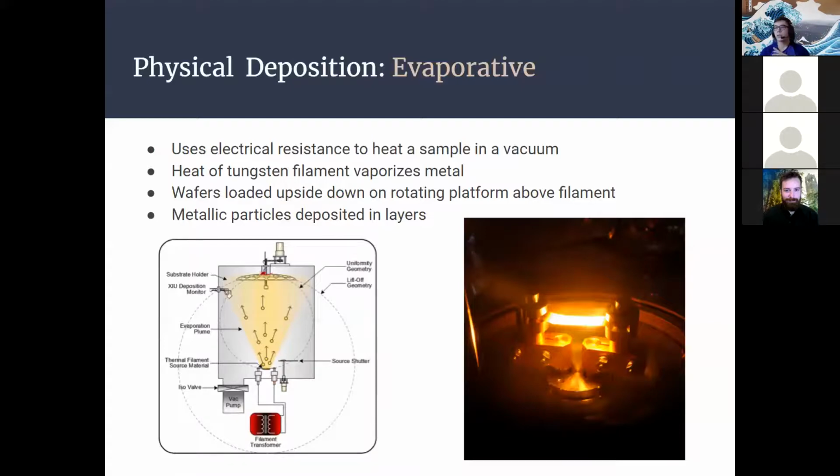But the limitation of this is that it's essentially dependent on everything having a direct open path, which can be a little bit difficult considering that you need to have some method of actually attaching the wafer to it, which usually can be done via vacuum. But in our case in the teaching lab, we were using smaller wafers than the machine was designed for, so we had some way to clip it on, which ended up requiring us to cover some corner of the wafer with a bent piece of metal, and obviously that prevents that area from getting covered by these released ions, or not ions, but these metal vapors.